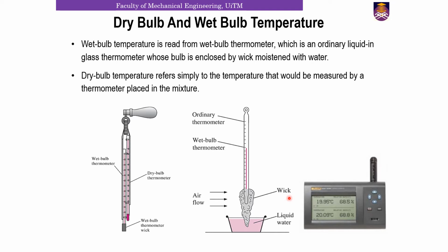The measurement here is actually based on the capacitance change in a thin polymer film as it absorbs water vapor. The device is capable of sensing and digitally displaying the relative humidity within 1% accuracy. So that is the modern device that we have nowadays. This was the earlier device that is becoming almost extinct. You can find this in a lot of museums nowadays.